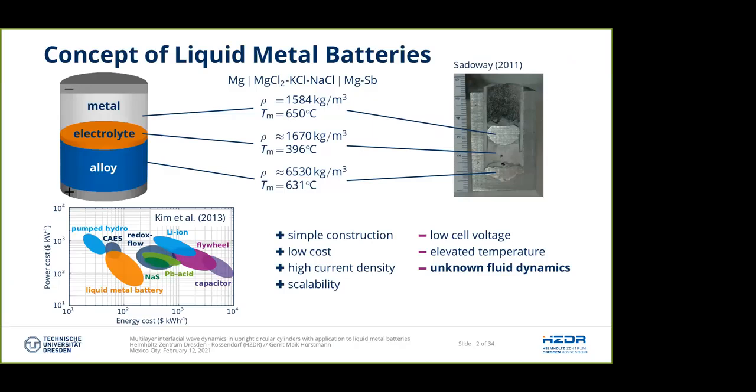So at first, before speaking about fluid mechanics, I want to shortly introduce the main concepts of liquid metal batteries. I think many of you are already familiar with these batteries, so I will keep the introduction short. But just to give you a first idea, the idea is to fill 3 immiscible liquids into a tank, which can be cylindrical or also rectangular in shape, and must have electrically insulating side walls. And due to the immiscibility, the liquids will form a stratification like here due to gravity.